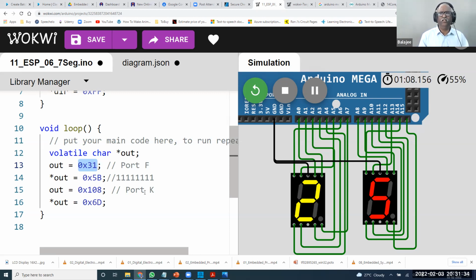That's a trick. If you write an Arduino-style program, with set pin, digital write, and pin mode, unfortunately that will not be available in other companies. That's the reason they want you to understand it as an embedded engineer. They want you to understand the pointer and the address and write it that way. That way you should know. This is given by every company.